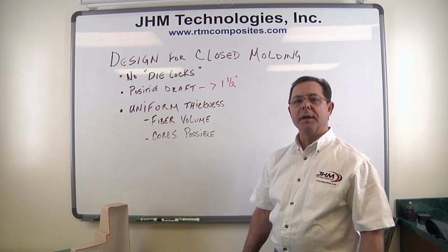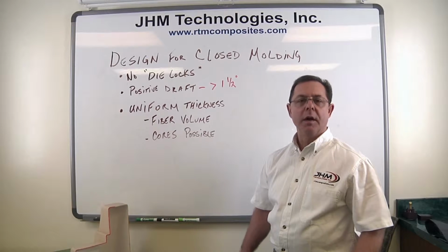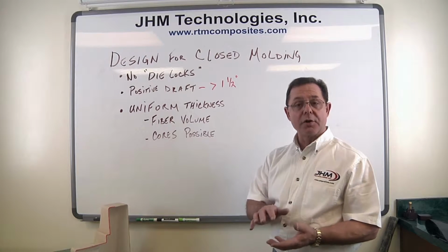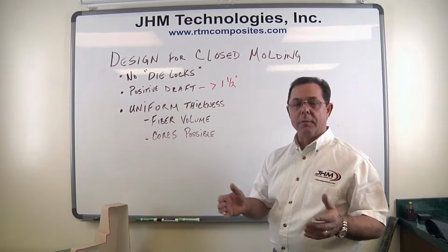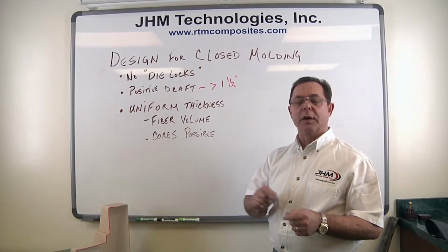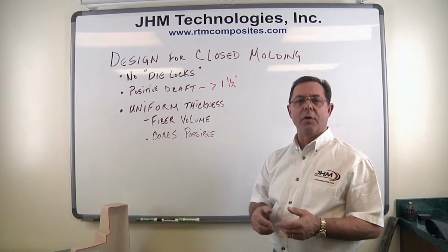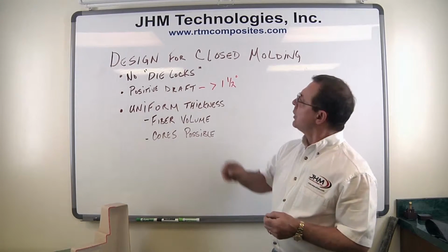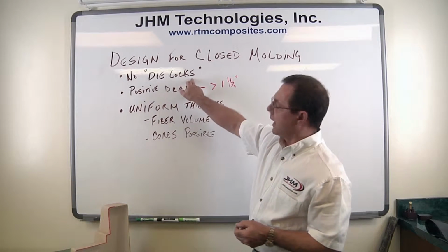Here today we're going to talk about designing for closed molding, whether that be RTM, light RTM, high pressure RTM, even VARTM. We all have the same concerns for these processes regardless of the acronym or the method that we're actually going to be molding. We're talking here about the part design. So the first thing is that we can't have any die locks.